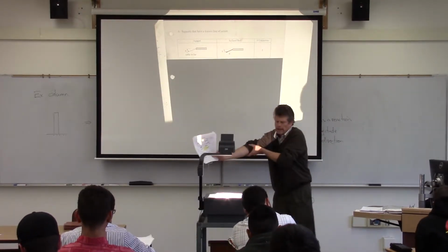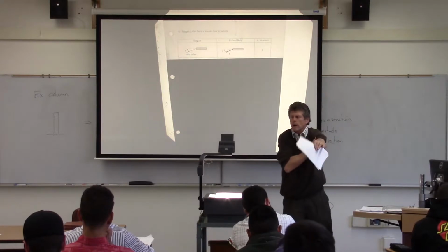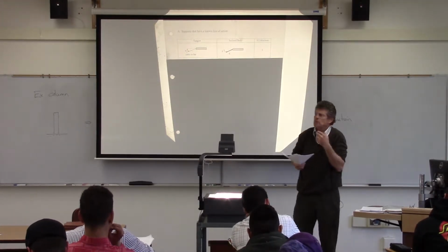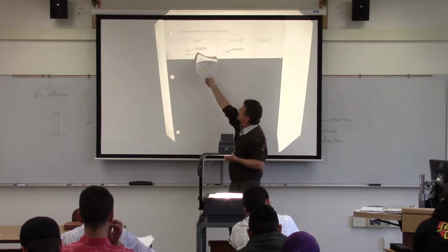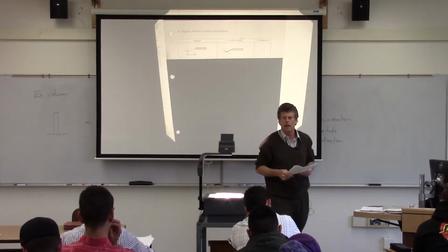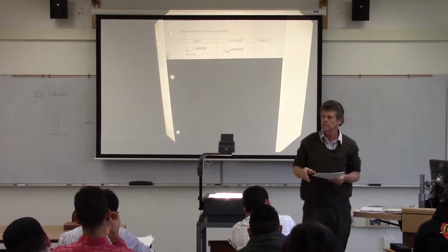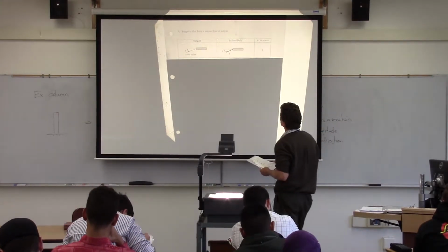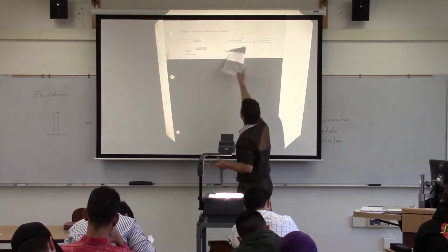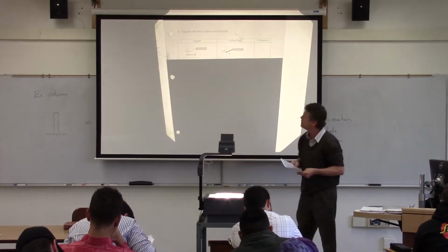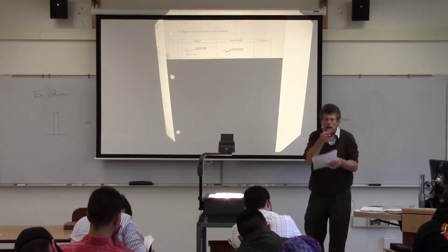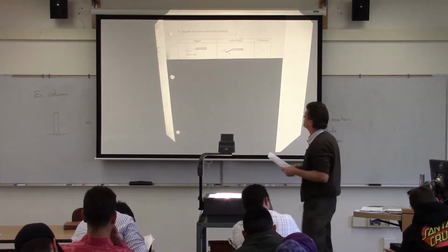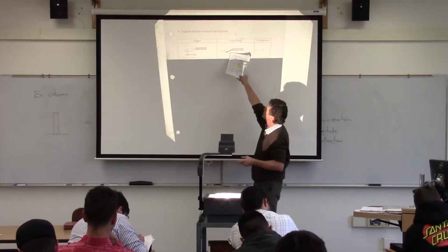Now, probably the easiest, and this isn't necessarily a support, although it could be, a cable could be a support, but again, it's another attached body. So there's a cable attached to that. Now, the nice thing about a cable is we can go out and measure it, and we can figure out what its angle is with respect to our isolated body. So our isolated body doesn't look a whole lot different. It's that bar there. But now, when I cut it away from that cable, so the cable suddenly disappears, I'm going to substitute in a force.